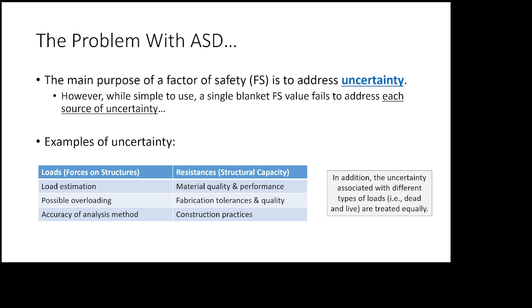What I'm getting at is, even though there were machines involved in the construction of these tables, and these tables were generated in an industrial setting, if you were to take a laser micrometer scanner and compare, underneath this there were holes that were drilled to connect the legs and whatnot. They're going to be a little off, right? The machine that drilled the holes might be precise to within 1/100th of an inch, right? So if you actually looked at them, they're off a little bit, right? That's what machine tolerances are for, right?